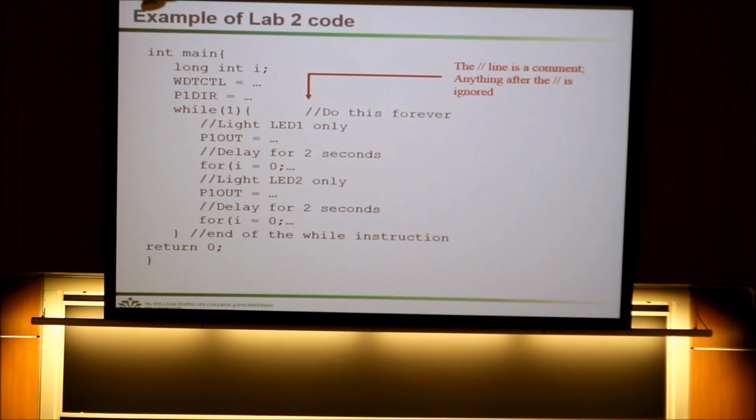And you already know what a while does, right? But notice I say while 1. What does that mean? That's one very important characteristic of embedded systems: when you say while 1, it is going to operate forever. And if you think about that projector and that wireless node, the cameras, etc., you never want them to stop running, right? So you'll always have a while 1 line somewhere in your code, which means it will go forever.